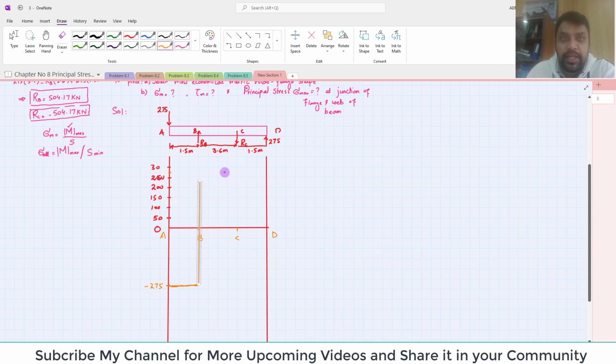Again from B to C there is no load, so the shear force will remain constant between point B to C. But at C you can see there is a force that is minus 504 and it is downward. So 229 minus 504 will yield you 275. So again you have to go to 275, and 275 is the same point. So you have to go downward till this point. Now again from C to D there is no force, so it will again be a straight line. So this is the shear force diagram for the beam.